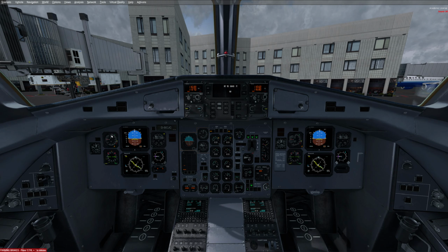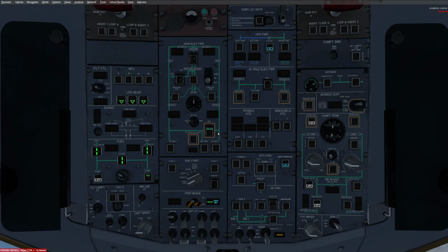The orange one is the only one you can do by wheel. The rest are done by hand. The N2 is what that orange one would be. Takeoff torque will be around 90. That's already there. Fuel pump now, number 1. Let's go ahead and start the second engine.